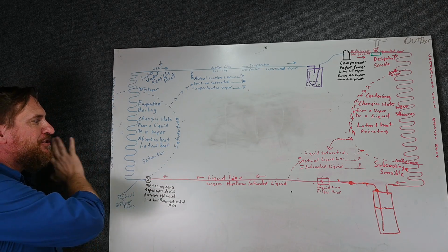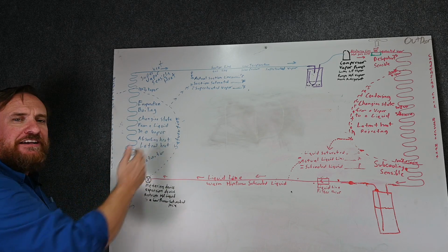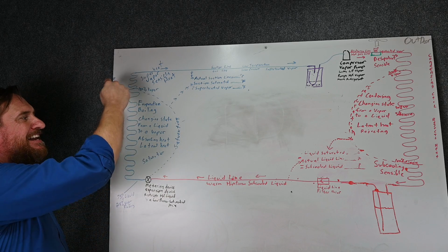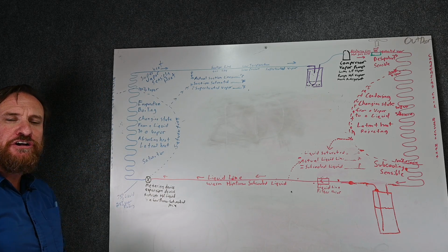Another thing is the temperature of the air is going to affect my suction pressure. As the temperature of the air goes up, my suction pressure goes up, and as the temperature of the air drops, my suction pressure also drops.